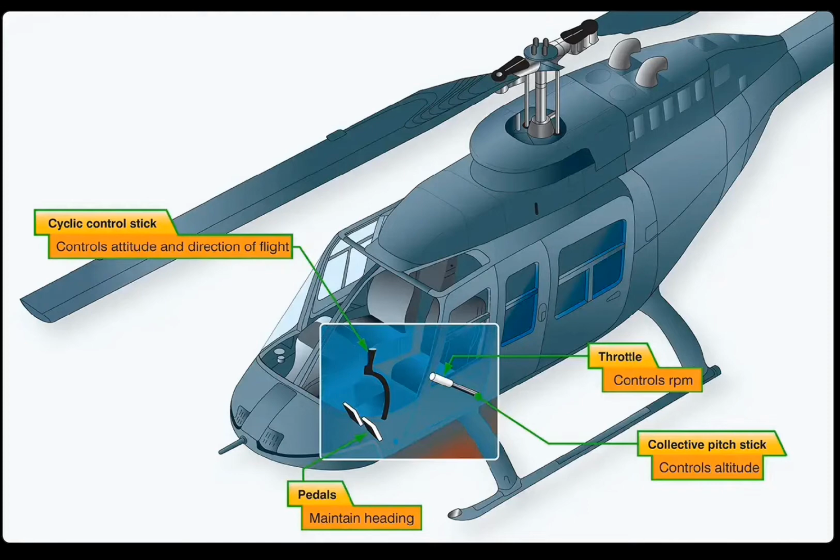When installing an aircraft bolt, what precaution would you take regarding the position of the bolt? Bolt head up or forward on any install. How is the propeller torque corrected for during assembly and rigging in some small engine aircraft?